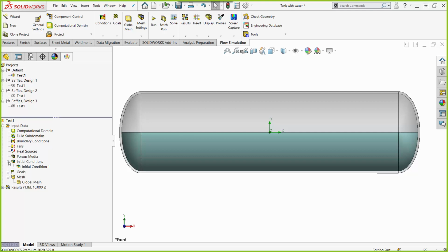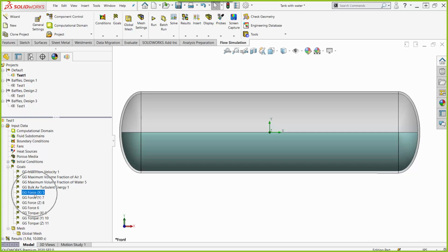I'm going to talk a little bit more about extra options, things like goals and mesh. So in my goals, these are the things that I am choosing to track because it matters most to my design. For a tank braking, I mentioned a few questions at the beginning of the webinar. I was saying I cared about force in the direction of braking, so the x direction.